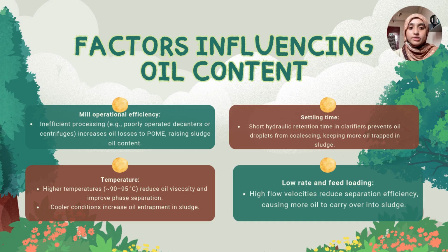For factors influencing oil content, the first one is mill operational efficiency. Inefficient processing increases oil losses to sludge, raising sludge oil content. And the second one is settling time. Short hydraulic retention time in clarifiers prevents oil droplets from coalescing, keeping more oil trapped in sludge.